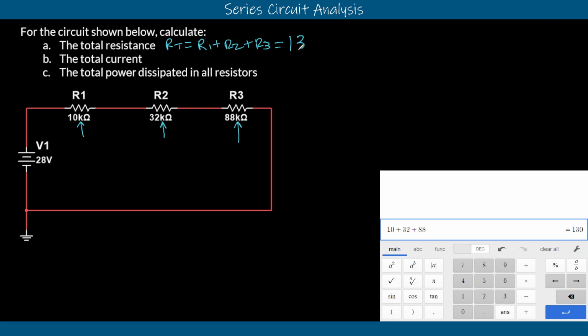So 130, and then I can just add whatever the ending was for every one of these resistors at the back here. That works really well when all of the resistors are in the same notation, right? They're all in kiloohms. But if one of them's in megaohms, you've got to make sure you remember to account for those zeros that megaohms represents.